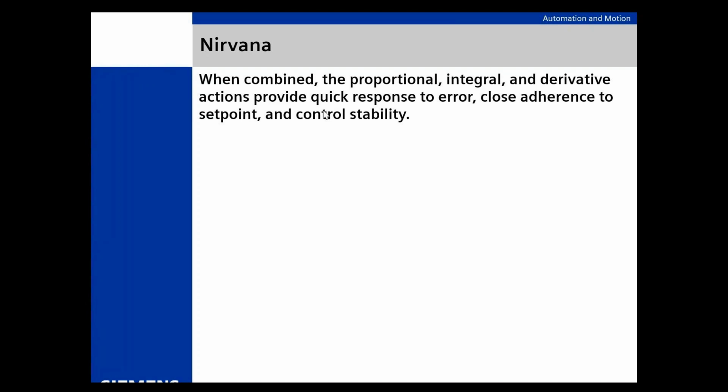The best way to do it, like I said, if you can, is sit down with this and write a ramp soak program. I want to go up, let's say, up one pH of 1. I'm going to go up 1, and I'm going to stop. And I'm going to see how much that keeps drifting. Because, again, I got a chemical reaction going on. That's not instantaneous. It's horribly nonlinear.